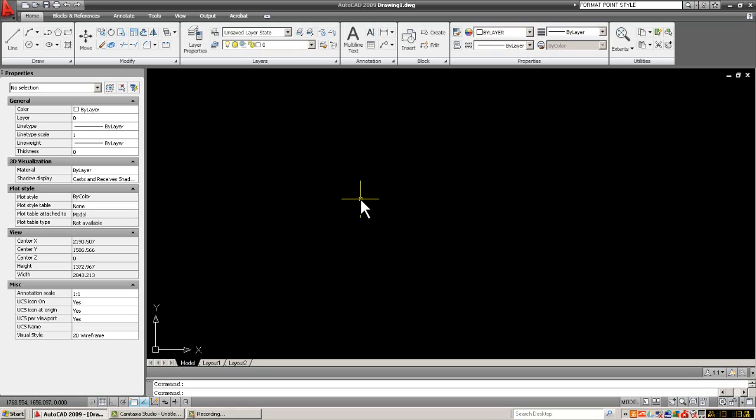Now what I'm going to do is, in New Zealand we sort of work in total coordinates quite a lot, and a lot of surveyors do, and the system that we work in typically has an origin of 800,000 and 400,000 currently. So when we're working on little projects on an assumed origin, I'd maybe stick with a similar sort of regime, and I like to call my assumed coordinates 7,000 north and 3,000 east. So in this little thing here, I'm just going to create a little point, which is the assumed origin of this assumed job that we're working on.